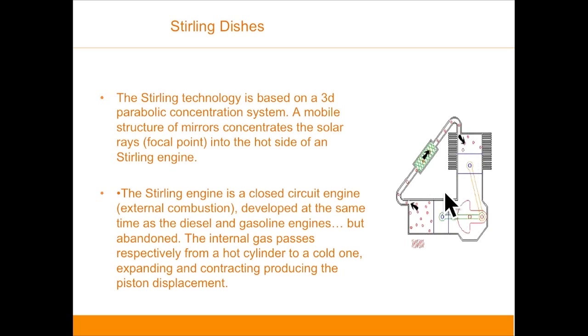When all the gas is in the hot cylinder, it is expanded, and a relevant internal pressure is produced to push that piston. From there, the gas moves to the other cylinder, where it is cooled and contracts, producing a lower pressure in the system. This variation of pressure, from very high to very low, is what forces the flywheel to rotate. So it's a very strange configuration.